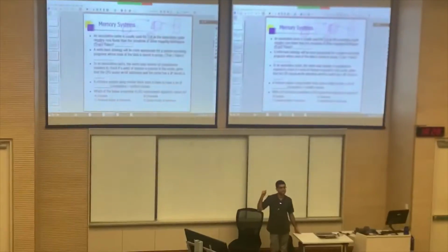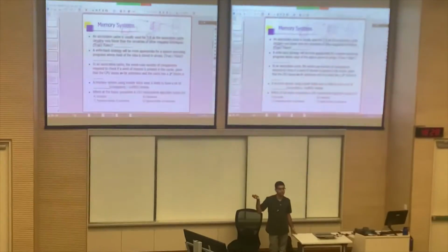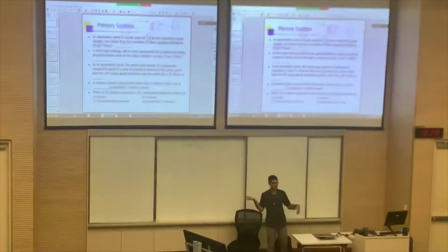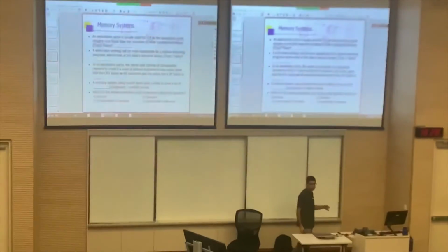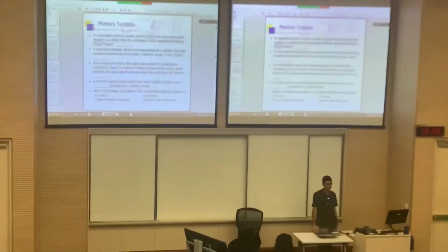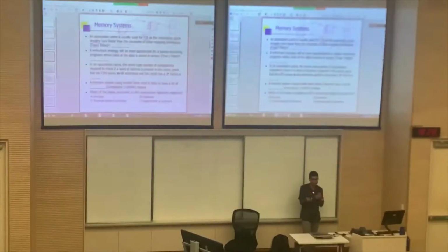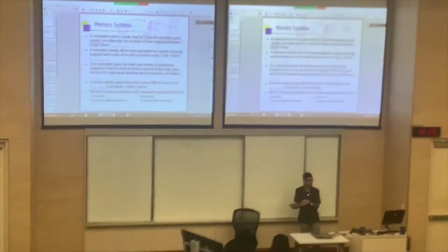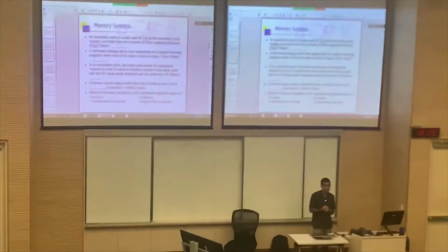Whereas for small caches, like if the cache can hold only 8 or 16 entries, then that search is quite affordable to be done for every memory access, right? Even though the circuitry is still not so simple, because 8 or 16 comparisons will require fairly complicated circuitry, the time taken is not so bad.